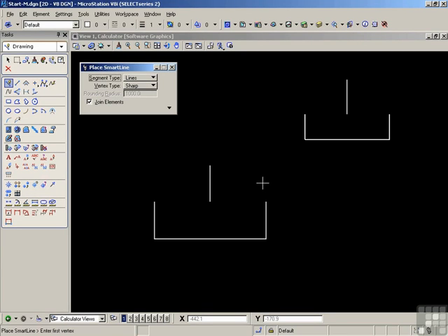As I mentioned earlier, the calculator will accept complex expressions, including multiple operators, parentheses, C expressions, trigonometry, and variables. You can also mix and match the format of the inputs, and MicroStation will interpret them correctly. Now let me add a couple of other shortcuts, not relating to the calculator at all. Clearly you're not going to remember every single shortcut, so you need to see a list of shortcuts as a pop-up on the screen. You can do this 2 ways.